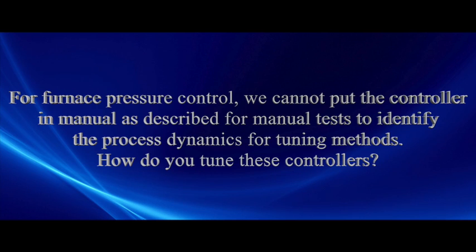Then we know how high we can go in gain. We look at the oscillation period and we get a rough idea of what the integral time is.